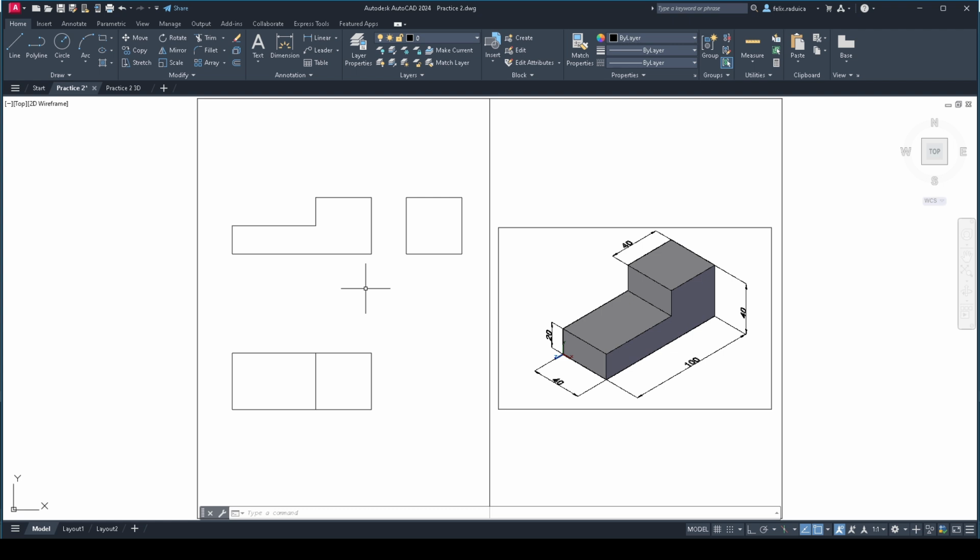And to finish up the drawing, we need the third projection. And the third projection is similar to the top projection in the sense that we can get the missing edge from the main projection, the front view. So if you look from the side here, we have all of the lines of the rectangle that we already drew, and we are missing one edge, which is this one, and it's at 20 millimeters from the bottom. So either I can project from here like that, or I can go 20 from the bottom and then like that. So let me type in the line command,